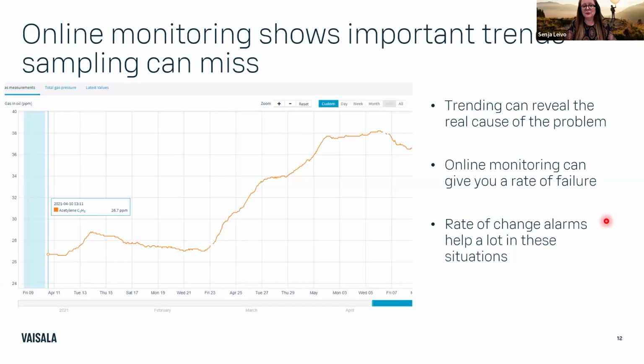The stray gassing world is becoming more complex, even with the new liquids becoming more commonly used. There we have different stray gassing patterns. So we may have ethane, we may have methane together with carbon monoxide. So it will become more and more difficult to identify stray gassing. Maybe the good thing to remember is that stray gassing typically appears with new transformers, or if there's been oil replacement or addition of some additives.